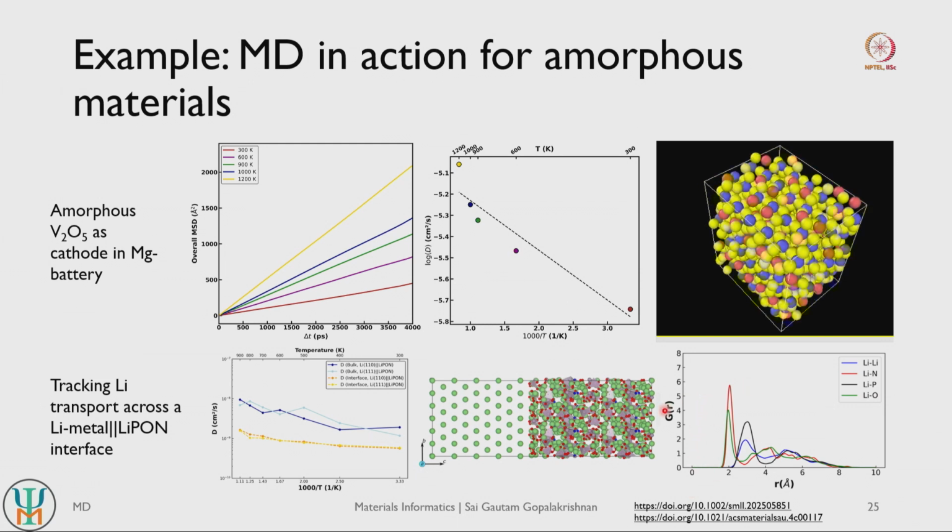And the nice thing to note here is that we are trying to model an amorphous system. So this is basically the radial distribution function for this amorphous system, and we see broad plateaus or shoulders appearing here, which is usually an indication of amorphization within the structure, because in a solid you will see very distinct peaks. We don't see such distinct peaks here.